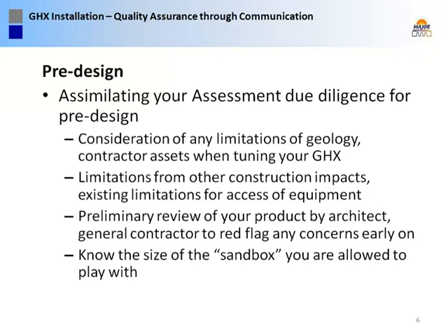What I like to do during pre-design is come up with a general site plan drawing, and I'll lay out the limits of the worst case size of the ground loop, what it might be, and then I'll fire that off to the rest of the construction and design team and ask for any red flags. Hey guys, are we going to run into this? Something that you can't tolerate or whatever. And it gives them a chance to comment early on.